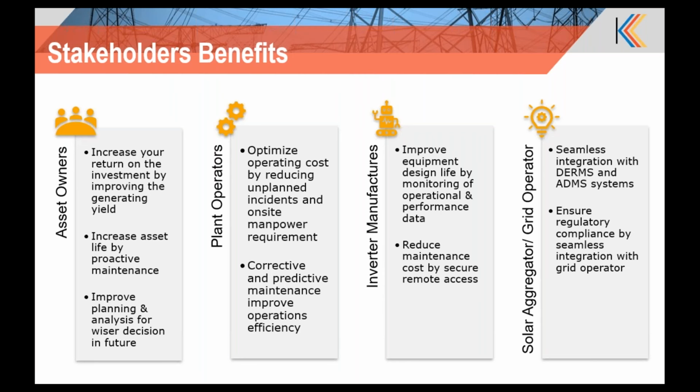To conclude, I'll just explain the benefits for different stakeholders. Asset owners who own a solar farm or rooftop solar commercial space can make use of this platform or solution to increase the ROI on what they have spent setting up the solar plants. It can be done by continuous monitoring of the generation yield, and it can also be used to increase the life of the system through proactive maintenance based on the data collected from these devices.